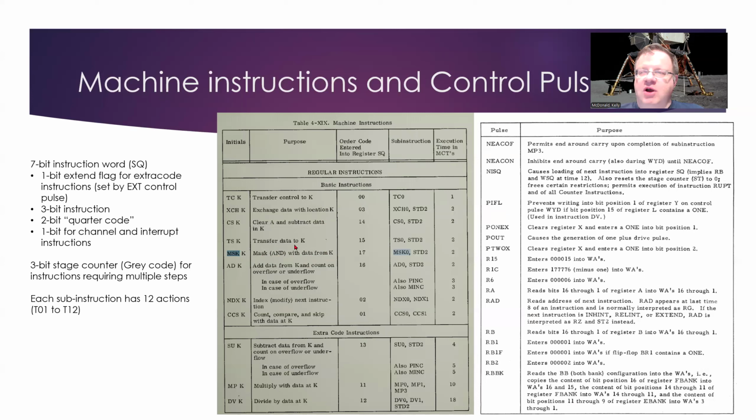Now, we've talked about the way that the Apollo guidance computer is a 16-bit computer, and the reality is it isn't quite a 16-bit computer. So the memory, the ROM and the RAM are 16-bit, and the ALU is also 16 bits wide. However, in memory, one of those bits, bit 15, is the parity bit. It's used to verify that the data being transferred from memory is in fact accurate, that it hasn't been modified or impacted in some way.